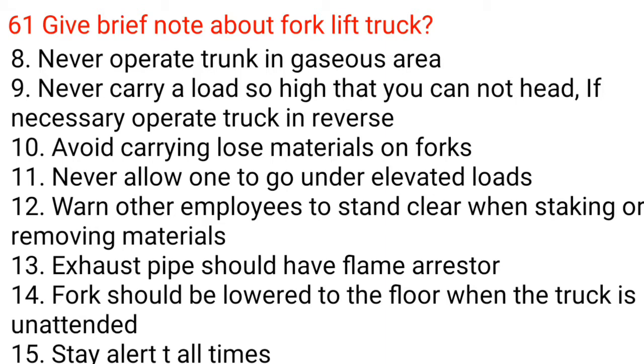12. Warn other employees to stand clear when stacking or removing materials. 13. Exhaust pipe should have flame arrestor. 14. Fork should be lowered to the floor when the truck is unattended. 15. Stay alert at all times.